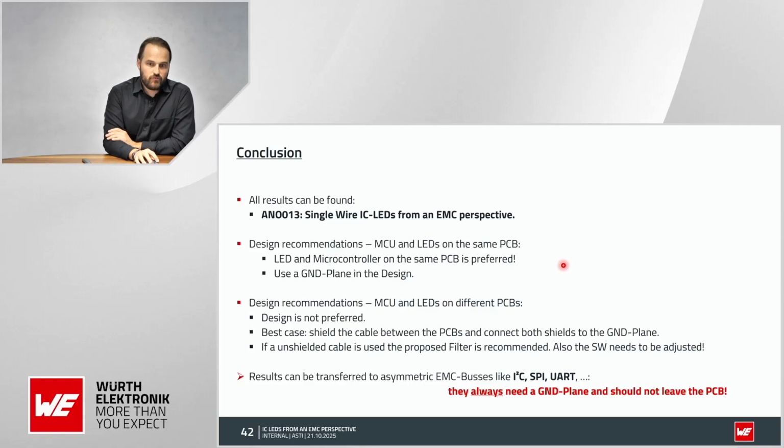If it's required to split up, because maybe you don't like to have your controller near your lighting panel, we recommend that at least you use a shielded cable. And if this is too cost sensitive, you can think of using a frequency dependent filter to deal with the frequencies that can occur. And for me, from an EMC point of view, the last point is even the most important.